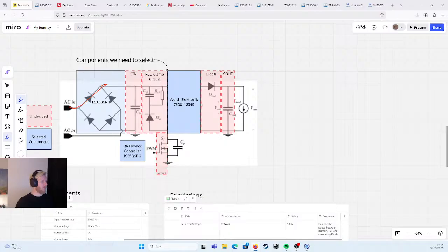Repetitive reverse voltage, bridge rectifier. It indicates the maximum voltage a diode in a bridge rectifier can repeatedly withstand without failing when reverse biased. So choosing a rectifier with a VRRM rating higher than the expected peak reverse voltage of the AC input is crucial for reliable operation, preventing diode breakdown and thus avoiding damage and ensuring the conversion of AC to DC.